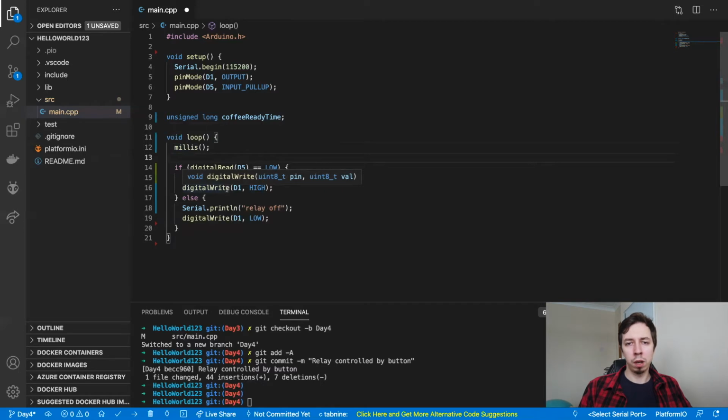We don't want the counter to go to zero, because this is essentially what happens when you reach the limit on integers, for example. It just goes back to the first value. If you use unsigned, which is only positive numbers, it's gonna start again from 0. So we really want to avoid this. It still can happen, but with unsigned long, it's just a longer time until it happens.